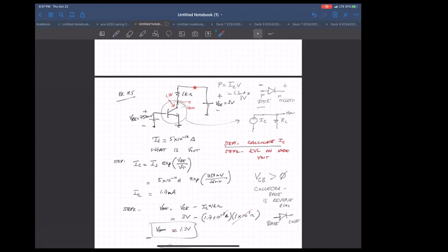Did you see what I'm saying? You reduce your power consumption by that much. Instead of 3 volts, you'll have 2.45 volts times the 1.3 milliamps. So there's a huge push.